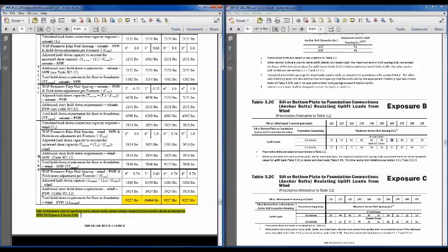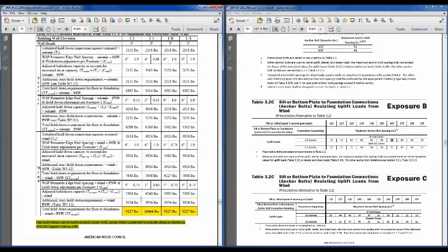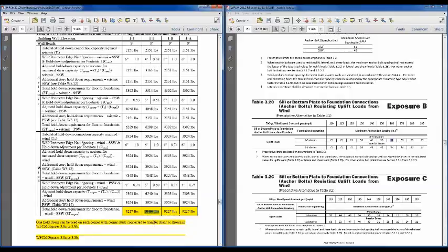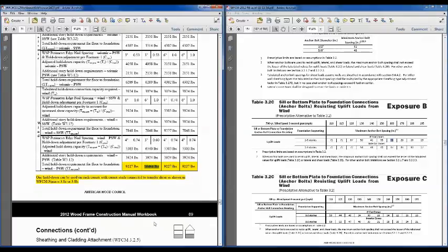You can take whichever one controls. If it's your load-bearing wall that controls, then you can use the larger of the two at those corners as the control. And for this particular example, looks like this wall 1-1 is the biggest one. So as long as you've got 10,500 pound hold downs at all your corners, you're good in both directions.